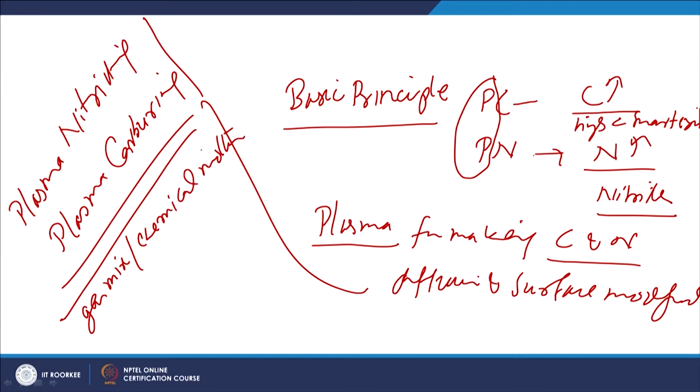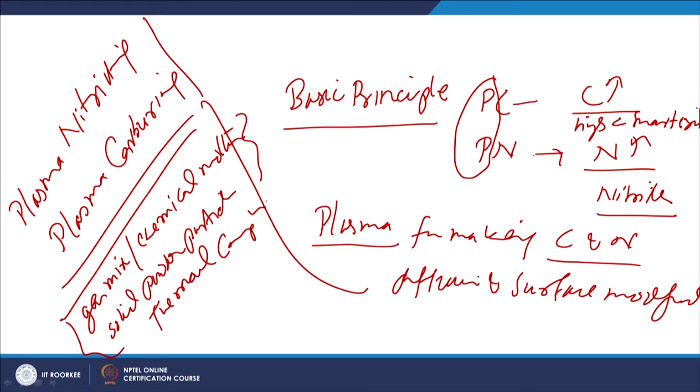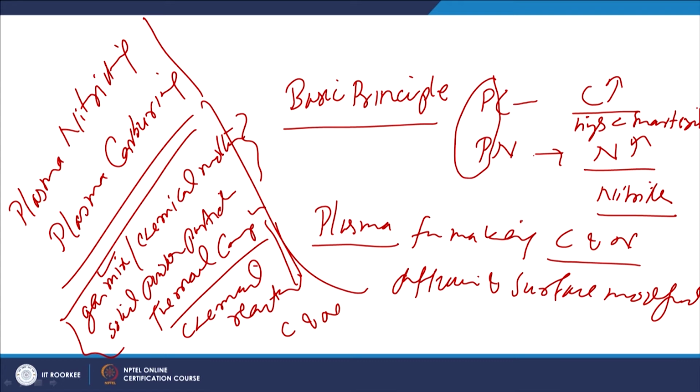in the form of a molten bath, or we use solid powder particles, and a lot of thermal decompositions are involved for making these required constituents into the carbon and nitrogen available for diffusion. So a lot of thermal decompositions and chemical reactions at a high temperature take place for making the carbon and nitrogen available for carburizing and nitriding respectively, and these in turn make the process slow and it needs to be performed at a high temperature.